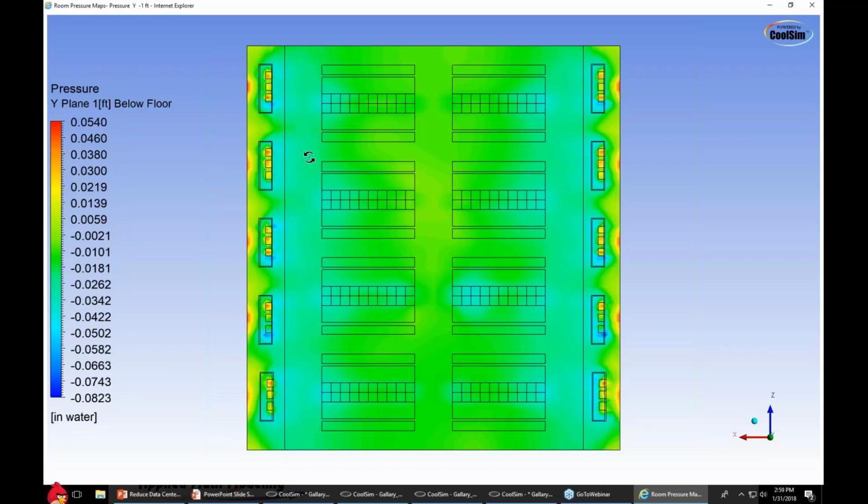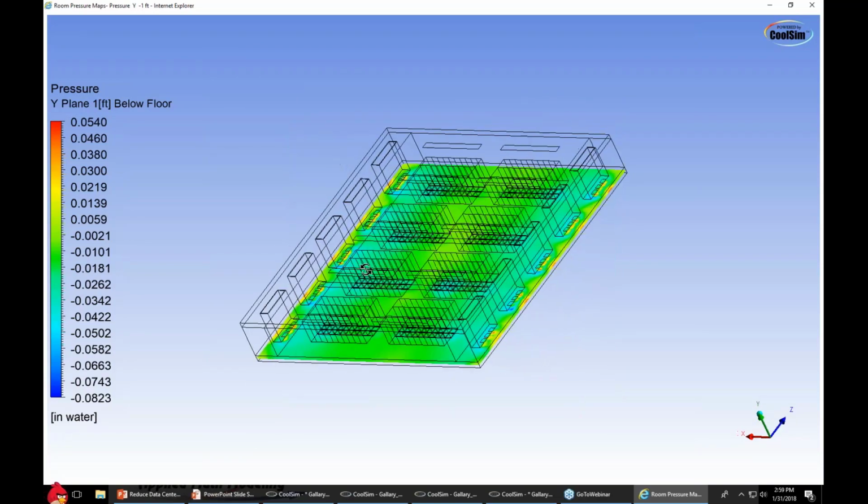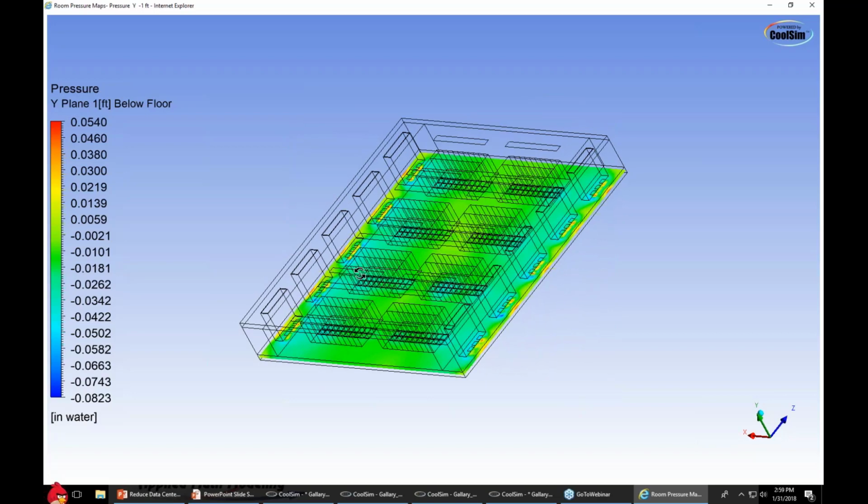Pressure is fairly low here. It gets high towards the middle. This is the highest because they're both blowing to the middle, so you have no momentum here. You have no real velocity. That's why it's highest in the middle of a room that's got perimeter cracks. So you probably would not want to put your pressure sensor here. You'd probably want to put a few of them under the floor, and it becomes difficult to know exactly where to put them. So I drive off temperature.